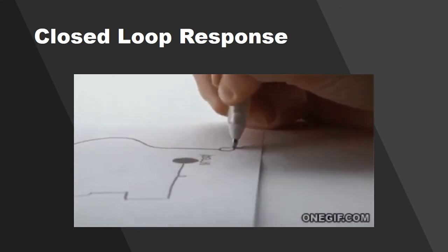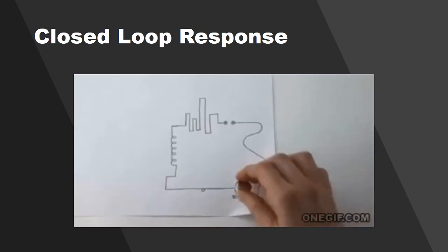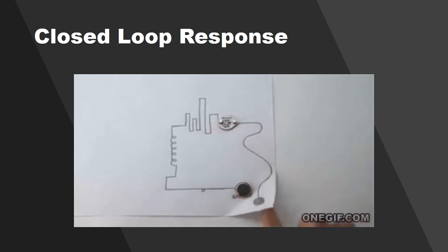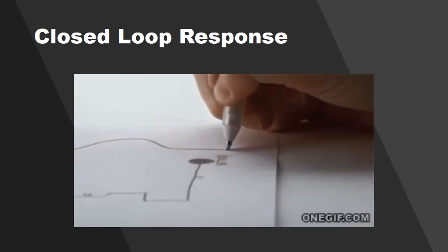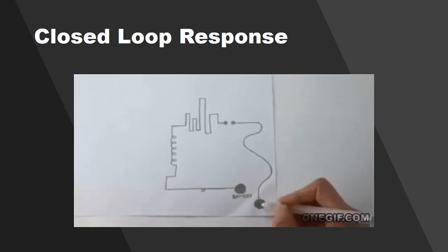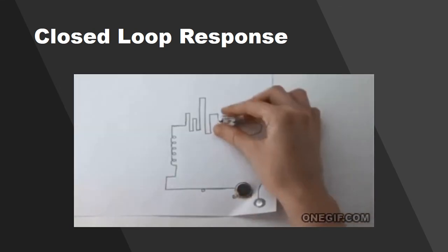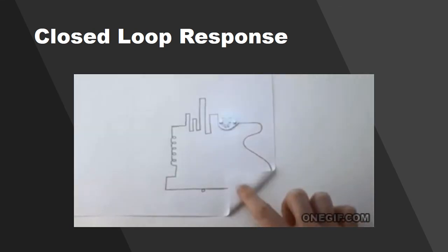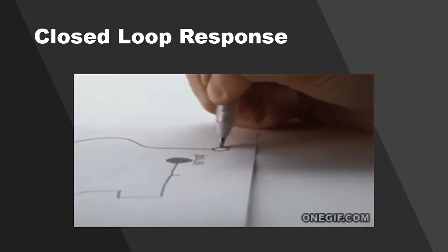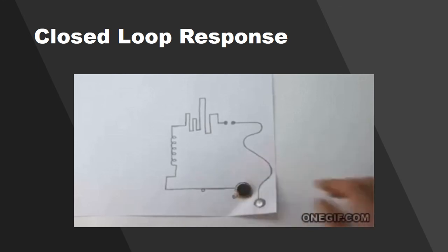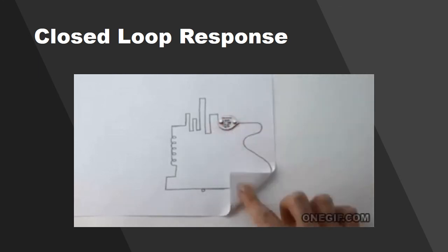Advantages for closed loop response: it has greater accuracy with the fine control of speed, improved dynamic response, motor operated at constant torque and constant speed, stabilized operations without any major deviations, and circuit protections can be incorporated into the closed loop speed control.